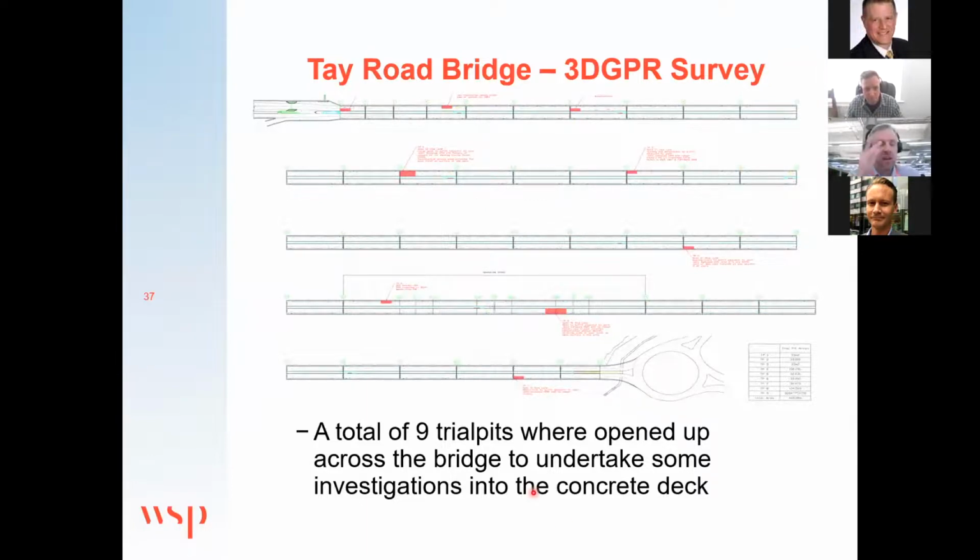Now, you're going to ask me, I know you're sitting thinking, what is the accuracy? So in the UK standard, the accuracy of radar is about 6%. Okay? What does that mean? If I have 100 mil material, then we should be able to measure within plus or minus 6 mil of that. Okay, and that's where our accuracy should be.